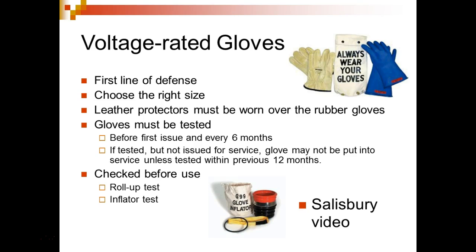It doesn't mean your meter can't handle higher voltages. You might have a meter that'll go up to 2,000 volts, but it's got a category 3 rating at 1,000 volts, right? You understand that? Then if you get above 1,000 volts, you're not protected against surges anymore. Your meter could do what? Could blow up on you.